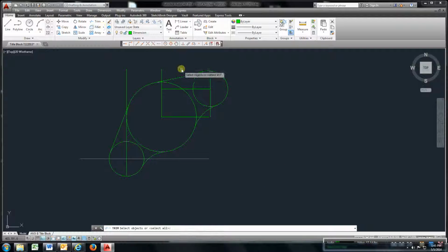Go to trim, I'm going to choose this line, that arc, this line, right click, we'll get rid of those, and I'm going to trim again off of these, left click, then right click, get rid of that, get rid of that. And I'm just going to use these other marks I have here. I'm going to leave those on temporary.